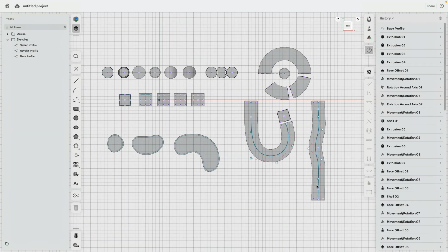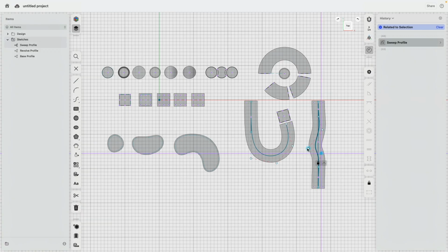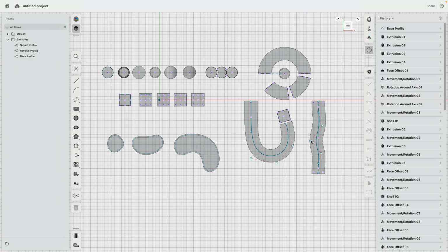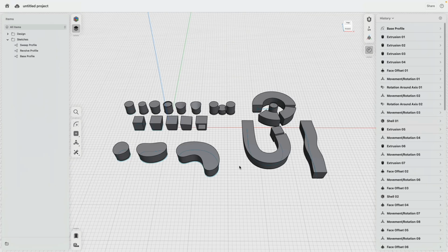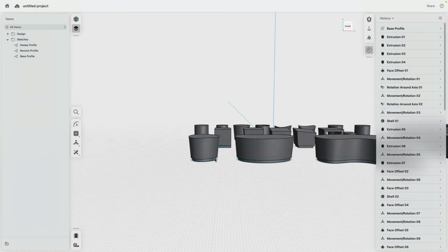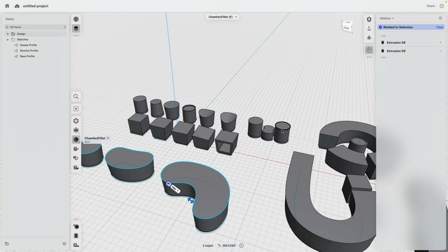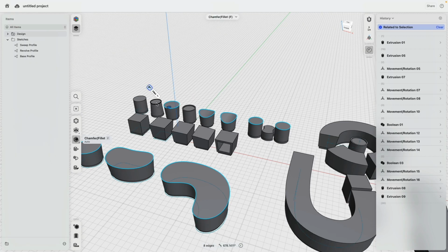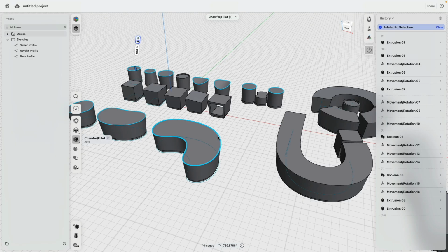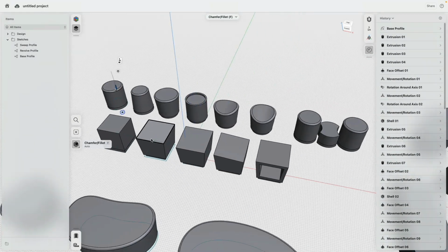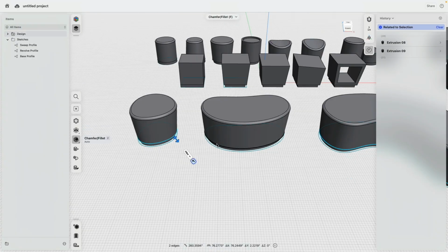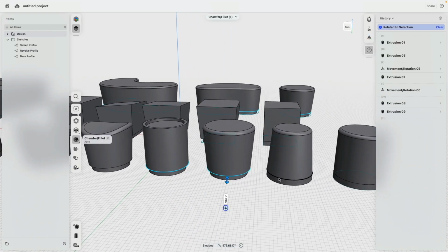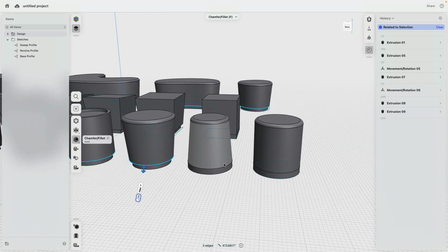Maybe last thing to fix is maybe bring this one up, bring this one over, bring this one there, and there, there, there, and there, and there. There's the midpoint. Yeah, that's good enough. Beautiful. And now is actually the task where we could go ahead and add fillets. Here, for example, this is all round. I select all those at the same time. So these are all the circular pieces. Let's say 1 inch. That's pretty good. And look, even there, this is actually really quite nice. So that's the bigger fillet on top, and then we can do the small fillet here at the bottom, 0.25.